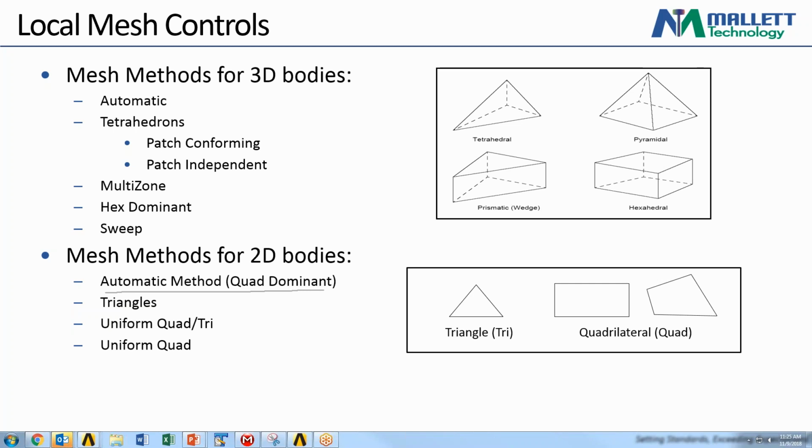Right? If you want to have a better pressure distribution across that contact, you could switch that to, I think, nodal projected from target, and that will kind of better smear the pressure across an element. Or you can just go ahead and refine that contact surface, right? And that should smooth out those contact pressures that you're seeing wrong, right?